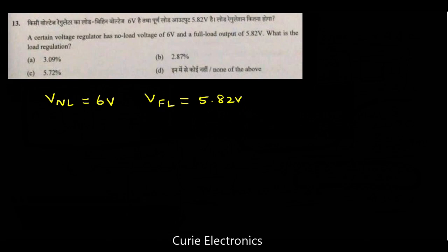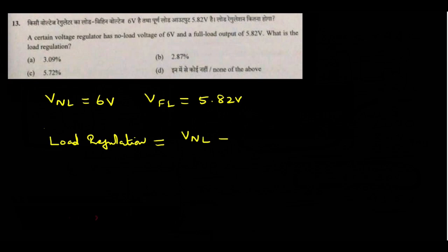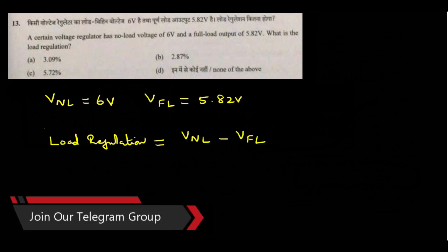For voltage regulators, load regulation is equal to V no load minus V full load upon V full load. This is the equation. So this equation you should know.